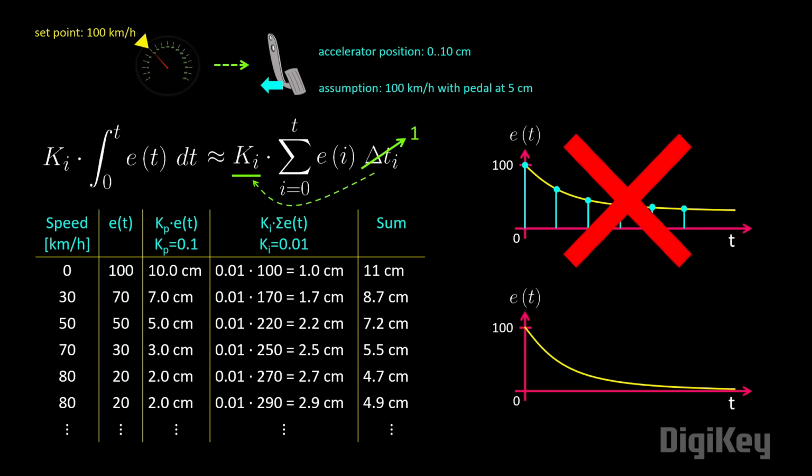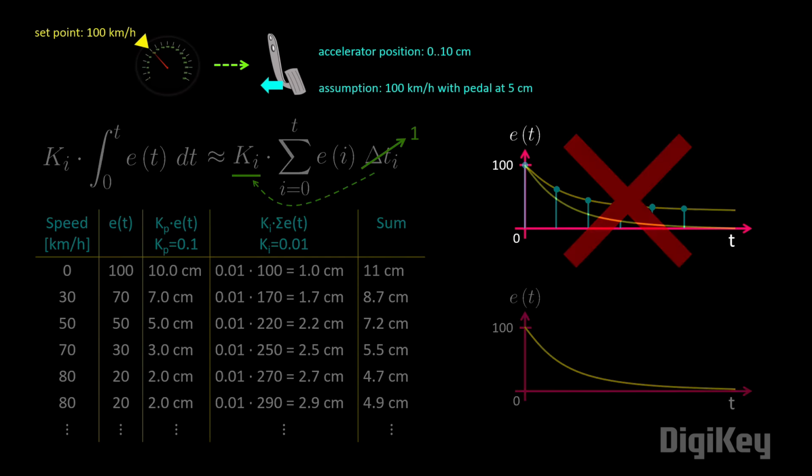The proportional and integral terms will reach a steady state when the error is 0, which means we perfectly hit our mark. In fact, in many cases, a PI controller is all we need. It's enough to move a process toward its goal while accounting for steady-state error. However, you'll often run into other issues that can't be solved by proportional and integral terms alone. A well-tuned PI controller looks something like this.